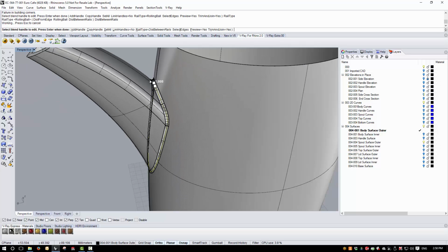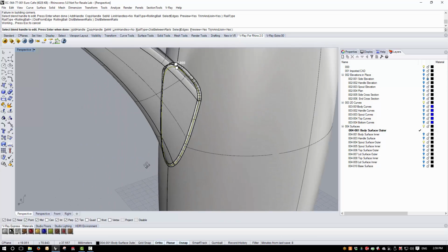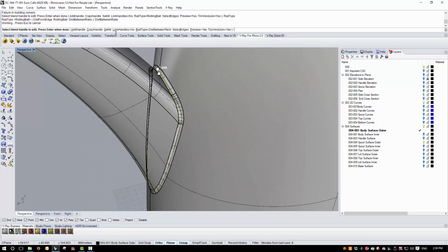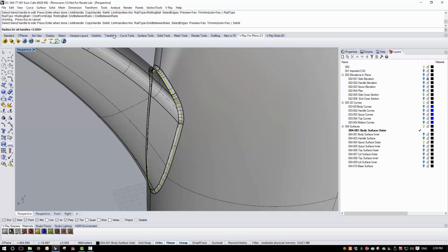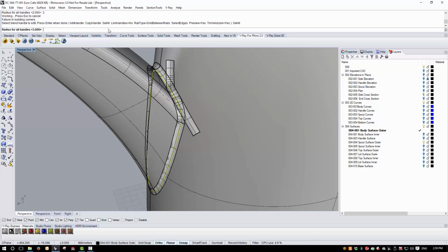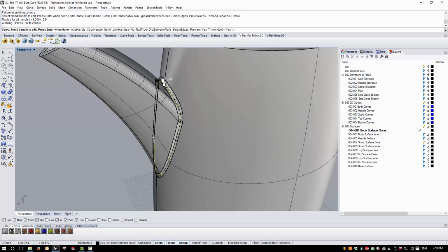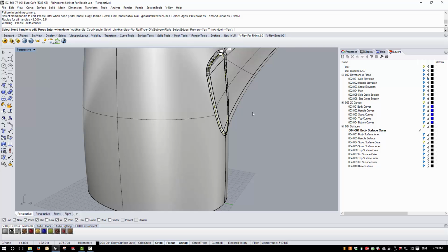This will give me a consistent looking fillet here where my angular condition is varying. And I'm just going to try and see if I can increase this slightly. If it's too big, it's going to fail. That looks good, 2.5 millimeters nominally there. So let's take a look at that.